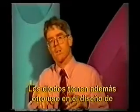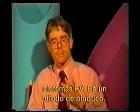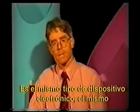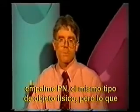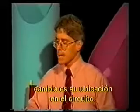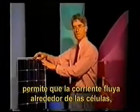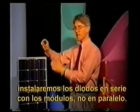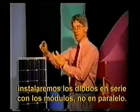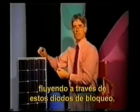There's another use of diodes in photovoltaic system design, and we call this a blocking diode. It's the same electronic type of device, the same PN junction, the same physical type of object. But now what's different is its placement in the circuit. Instead of having a bypass diode put in the junction boxes that allows current to flow around cells, we're going to install diodes in series with the module, not in parallel. So current from the modules now will always be flowing through these blocking diodes.